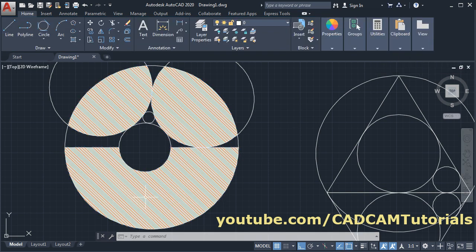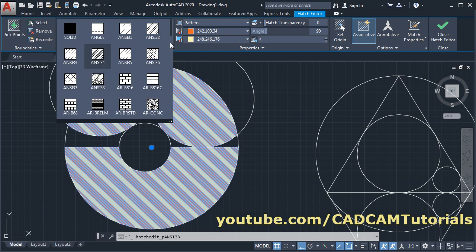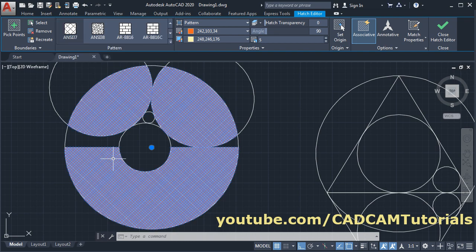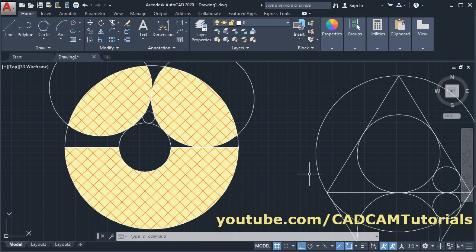And if you want to edit this hatch, or if you want to edit an existing hatch, then take your cursor on the hatch. Once it gets highlighted, then click on it. So it will bring up this hatch editor again. Then you can make any changes you want. Suppose I want to change the hatch pattern to this one. So as per that, it has been updated. Suppose I want a larger scale, I will make it 20. Once you have done all the changes, just click on this tick. So it will update your hatch.